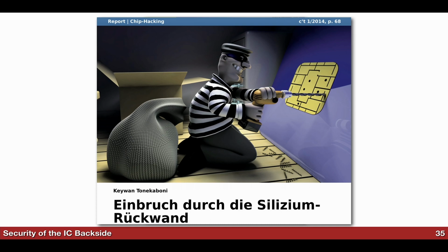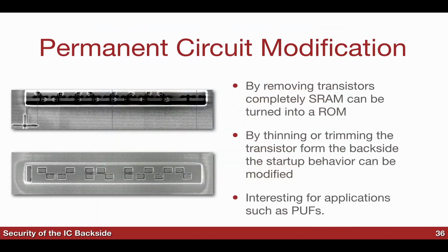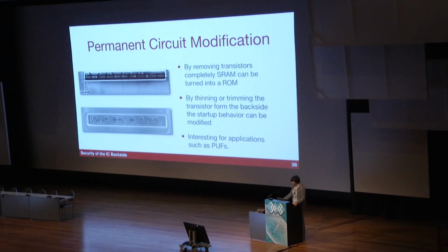Getting back to the SRAM, we knew what the SRAM was, so we could do a couple of things there. We would take a second SRAM array, and we would prevent it from ever storing the value that we didn't want it to store. So we would program it to only be able to store a 0 or only be able to store a 1. That's the top image. You can see the holes going down to the actual contact, so the transistor is completely gone there, or at least the gate. The gate's no longer contacted, even if some of the gate is left.